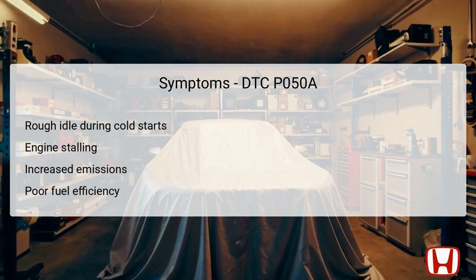Symptoms of the P050A error code may vary, but commonly include a rough idle when starting the engine in cold conditions. Drivers might experience the engine stalling unexpectedly, especially when coming to a stop. Increased emissions may result from inefficient fuel combustion, as the engine struggles to maintain the appropriate idle speed.